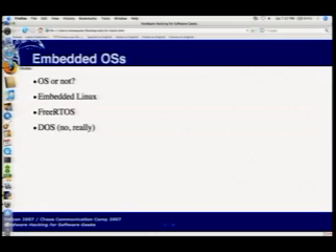That way you can ensure that everything's going to happen on time. For other more complicated things, you might have things running on timers, where this only executes every 100 milliseconds. Each task may have an individual timer, or they may all share a single time base where every 5 milliseconds this occurs, every 100 milliseconds this occurs, and you just set flags for when those deadlines have been passed.